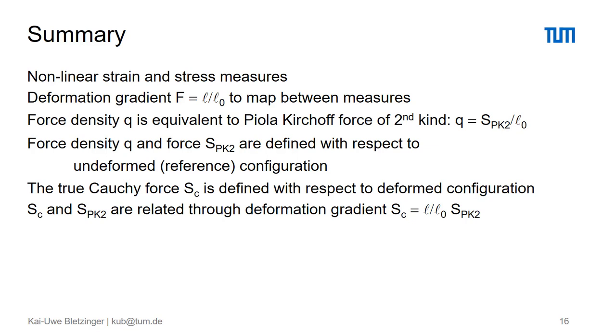We already come to the summary of this seminar. We had introduced nonlinear strain and stress measures necessary to be able to do nonlinear large deflection analysis. We had introduced what is called the deformation gradient F as a ratio of the actual length, the deformed length, to the undeformed length, which is used to map between those measures. And we have found that the force density Q is equivalent to the ratio of the Piola-Kirchhoff force of second kind and the undeformed length L0.